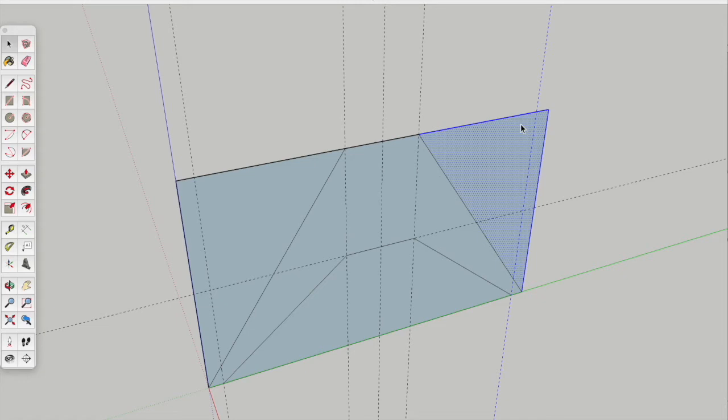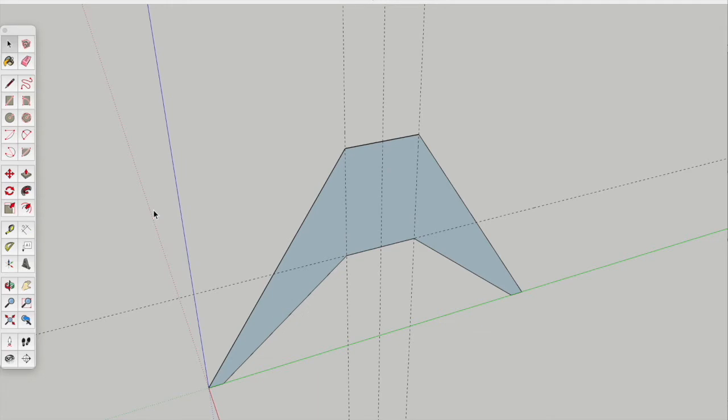The surface and the two lines, hit the delete key and it's gone. Same thing here, and same thing here. That's one of the real benefits of that function of SketchUp, where you can just drag from right to left and anything it touches gets selected. Anyway, let's move on. So what we need to do now, we have the shape we want.